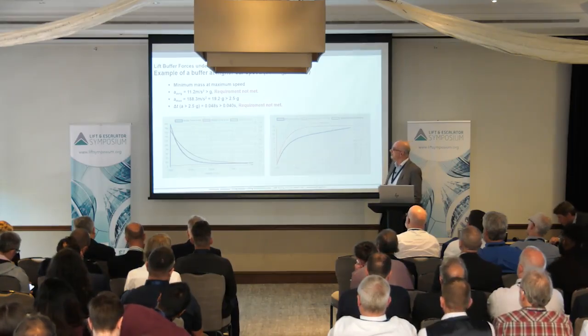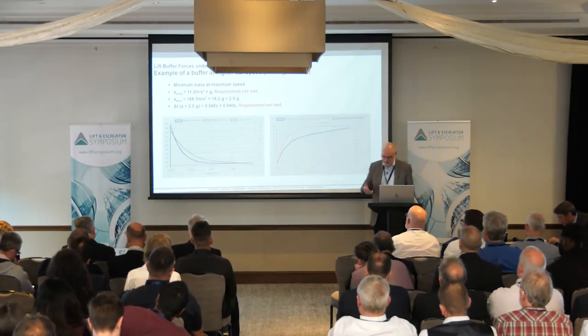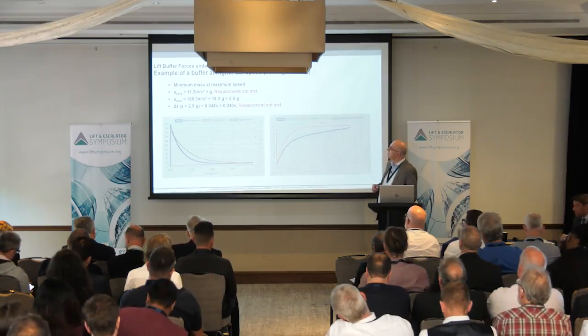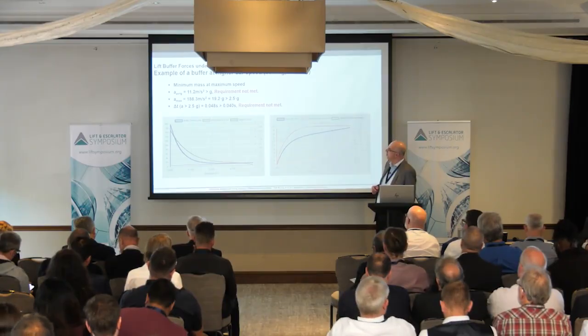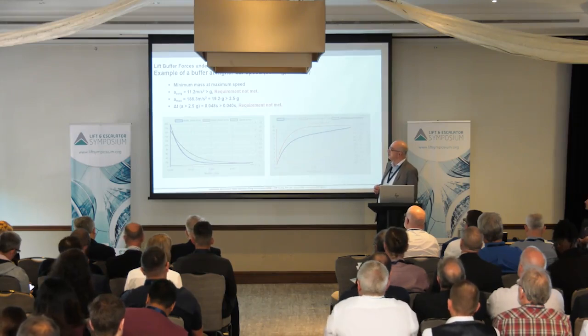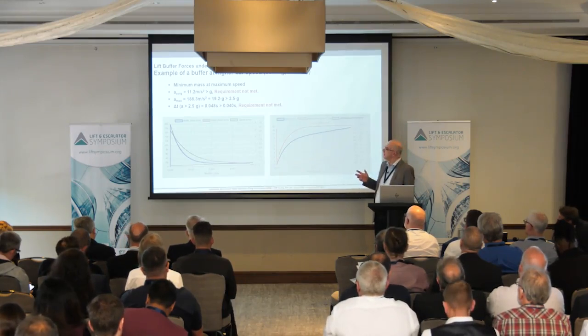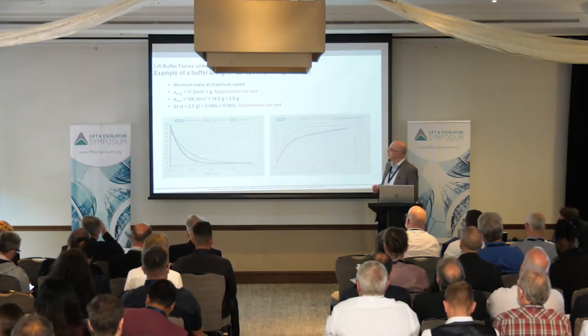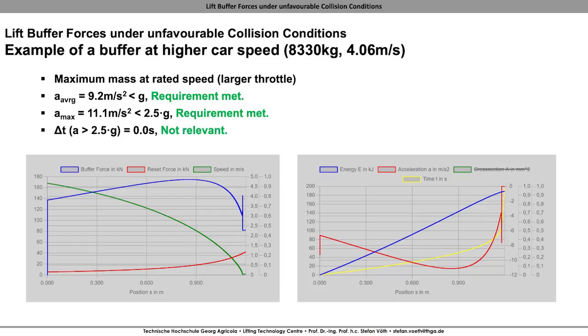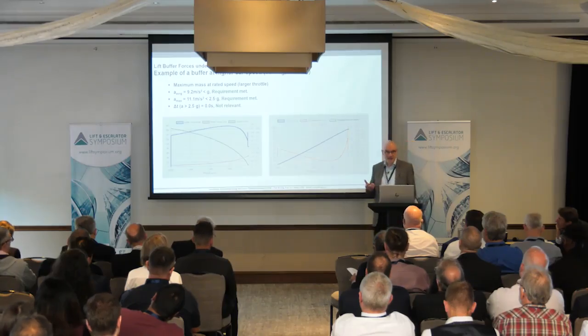It's not a real requirement for this case, but the general requirement of less than 1G average deceleration is not met anymore, and especially the high decelerations, very high, close to 20G, act for 48 milliseconds, so much more than maybe the target.